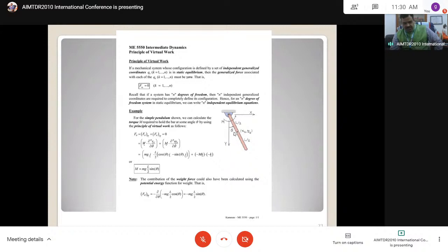This is L by 2 cos theta, which is vertical. L by 2 sin theta is horizontal. Okay. That's how we can resolve the component of mg downwards. The x component and y component, you find out with i vector and j vector. From here to here, L by 2. Sometimes you can use vector notation also, not only scalar notation. Rotation is about the z axis, M theta, M into k, because both are in the same direction, like z axis rotation.